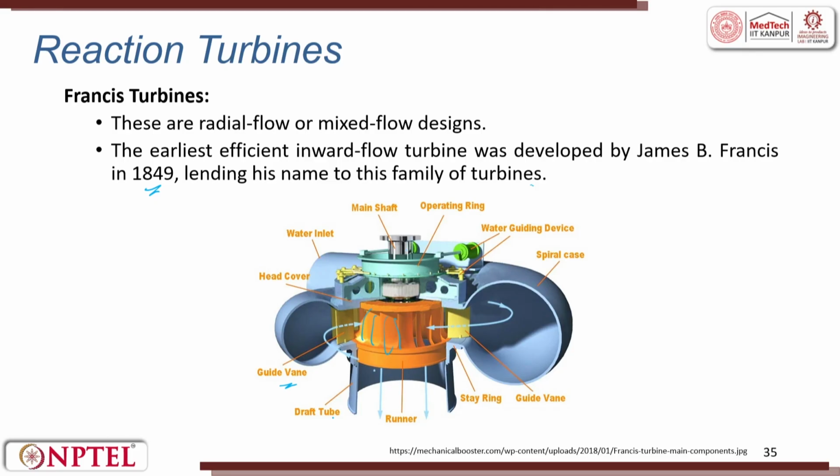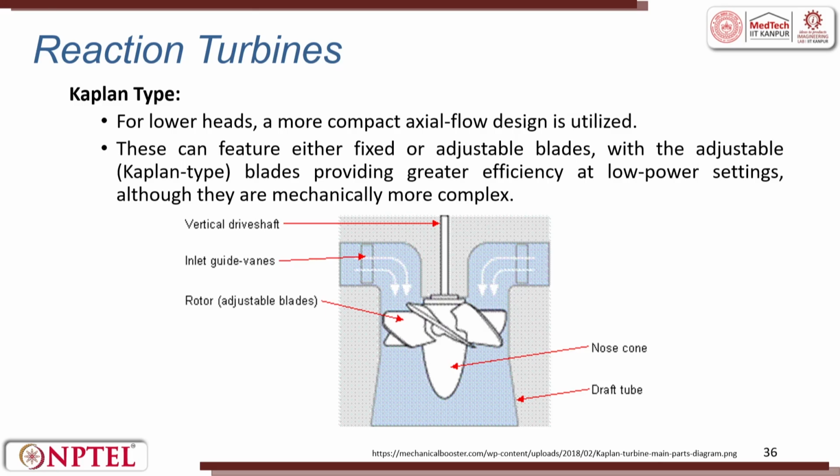Under reaction turbine, we saw Francis, now we saw Kaplan. So, for lower head, a more compact and axial flow design is utilized. We use either a fixed or an adjustable blade. These are blades where we can fix the profile, in the sense slot angle, with the adjustable blade providing a greater efficiency at low power setting.